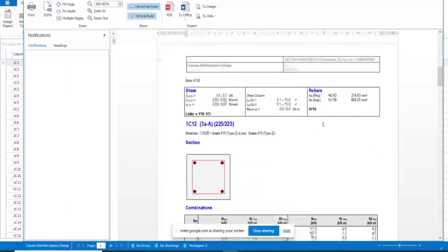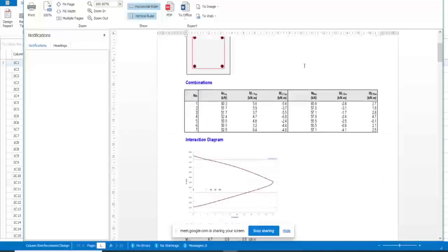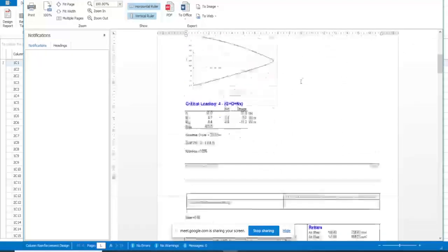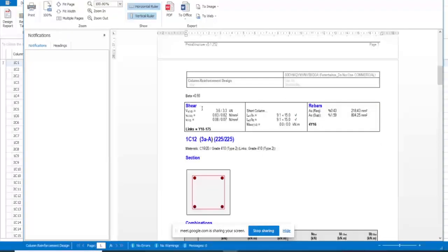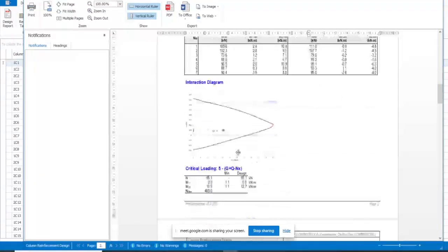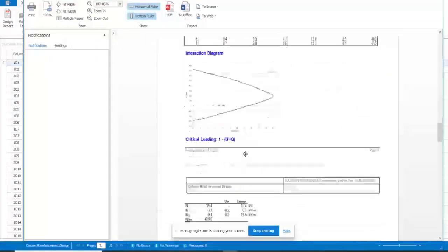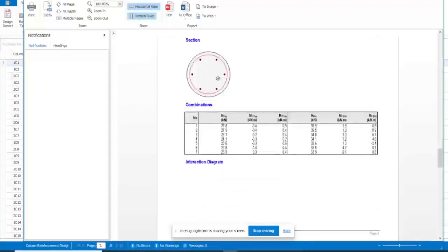So this is how to generate the calculation sheet for columns. See that? It gives you the shear force values. It gives you the ratio L over B and that of the additional moment or the reduced moment. Alright, we have the reinforcement, the area of steel required and area of steel supplied. So all through that you have all. To print this is a circular column.